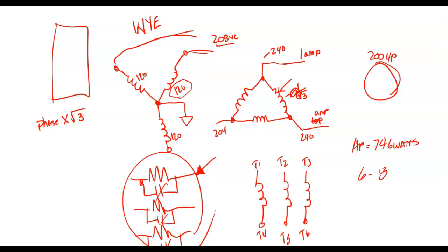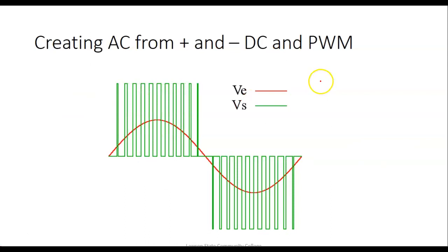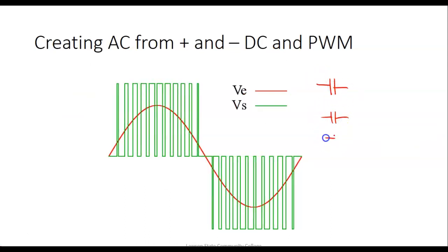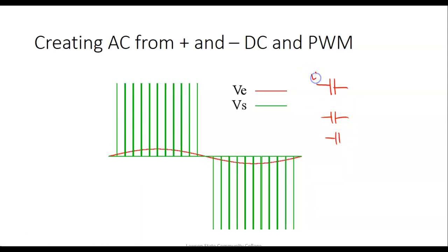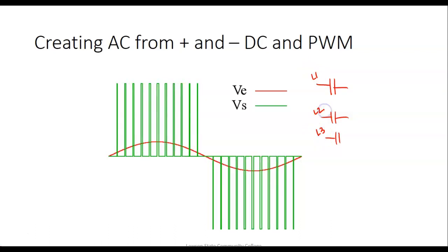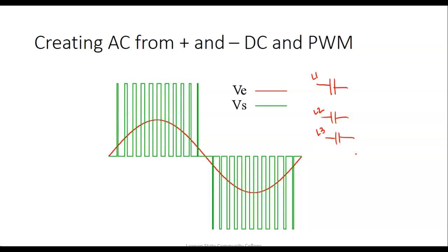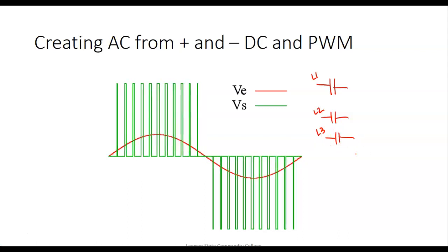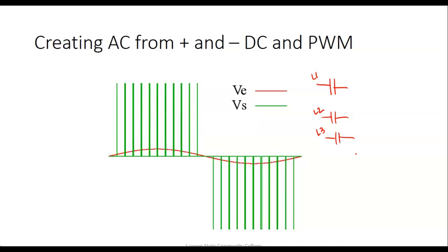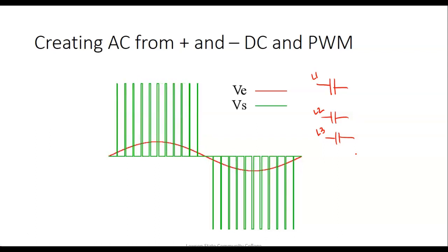Okay, guys, so that's about it. So how do we reverse the 3-phase motor? Normally, industry standard is swap L1, L2. But technically, you can do it another way. Well, when you do things, you want to do them according to what we call industry standards, so that the next person that comes in there after you knows what to expect, right? And if you don't do it according to industry standards, then they talk about you.